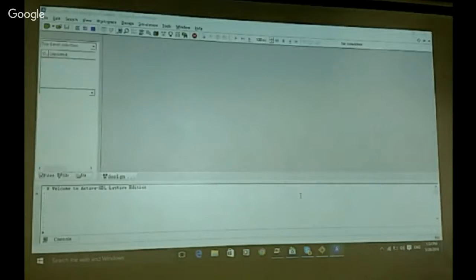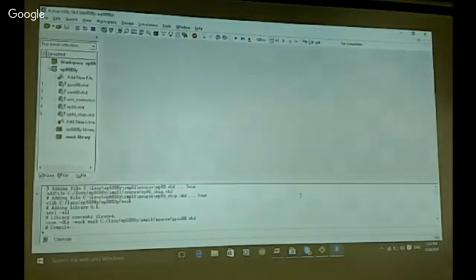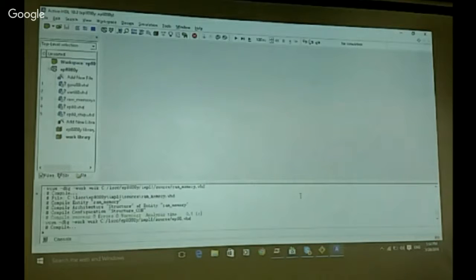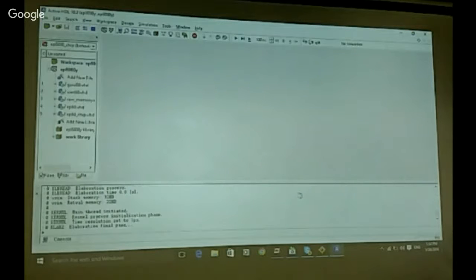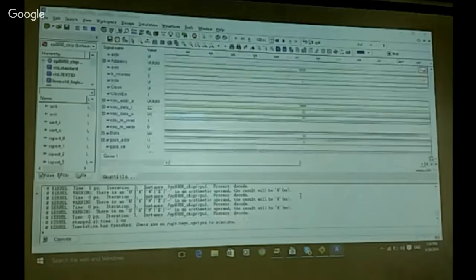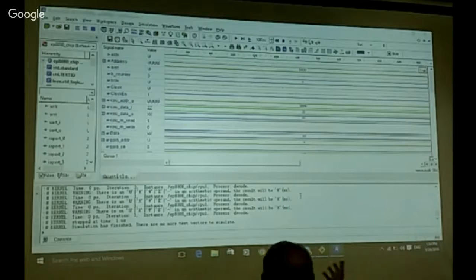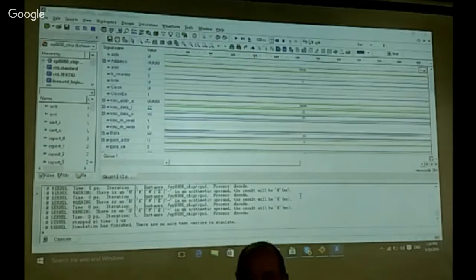Okay, so it is thinking, takes a minute or so. And actually, this HDL tool is doing the entire synthesis by itself again, and then produces the proper signals. So here we got nothing but straight lines. That's because we haven't specified the clocks and the reset.